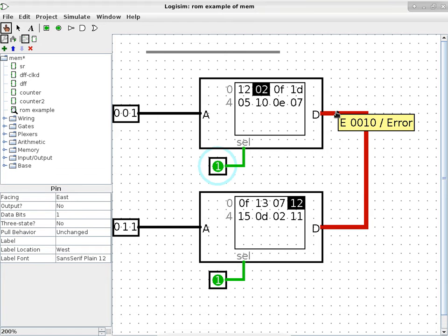Wouldn't it function like an OR gate physically because it's outputting 1 to this side? Nope. This is technically called a bus fight. Yeah, that's the technical term. It's called a bus fight because now you have one device trying to turn it on, one device wants to turn it off, right? Okay, so I'm going to draw this picture. I will draw it on the whiteboard because it is not going to be in a quiz, okay? But I do want you to kind of look at it this way.